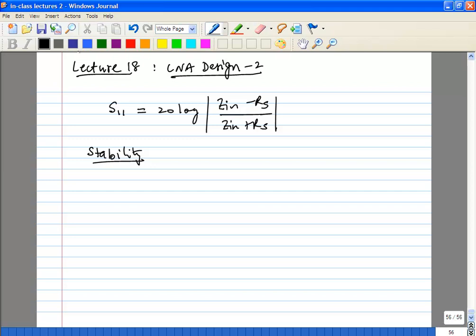But suppose you don't have to do that, then you don't do matching at the output, you would include the load of the mixer as part of your tuned circuit. So you would have to worry about S11, but there's no longer a problem with S22 and so on. Now we are still trying to decide whether we want to do output matching or not.